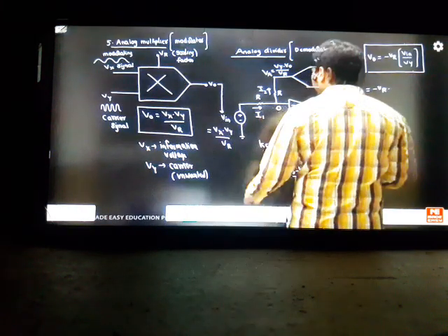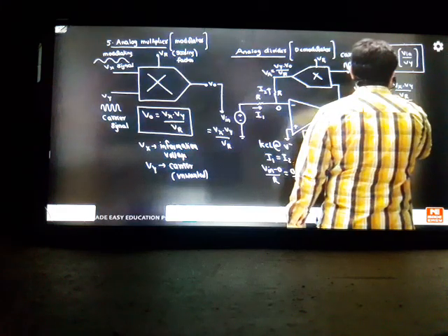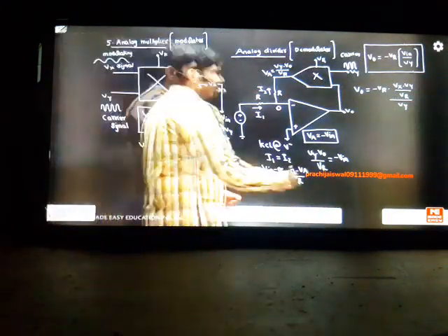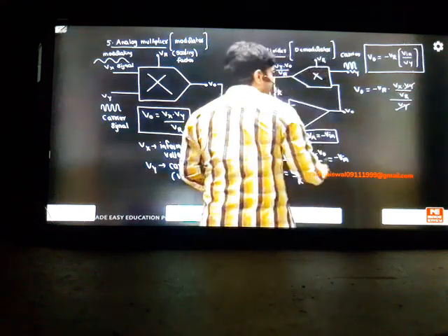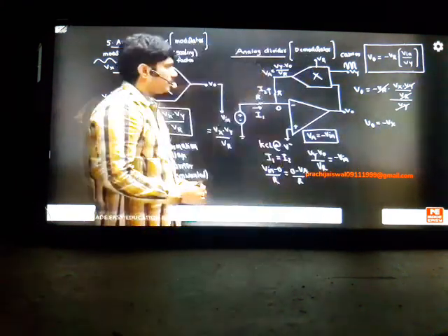Vr into what is Vin here, which is Vx into Vy, divided by Vr, divided by Vy. So this is the actual simplification, you can see how you are getting the output. So the Vy carrier will cancel, which is unwanted. Your scaling factor will cancel. So output will become minus Vx. So finally the answer came as output is equal to minus Vx.